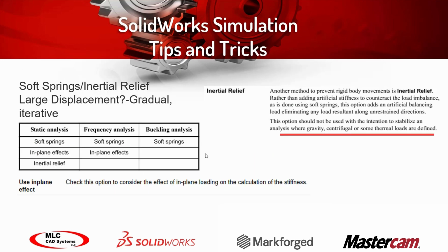Now, I had brought up previously that the only way that we can have an assembly or a multi-body part mesh in simulation and run with interference is by having the shrink fit condition. We go through an exercise using that shrink fit condition. It's an example as if you imagine an inner race of a bearing going onto a shaft. So we go through that example as part of our training class.